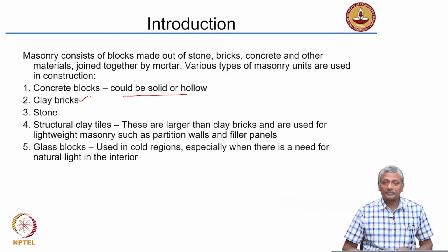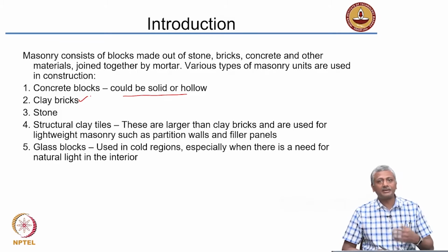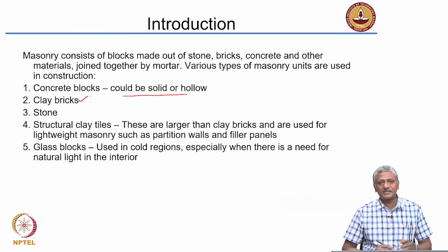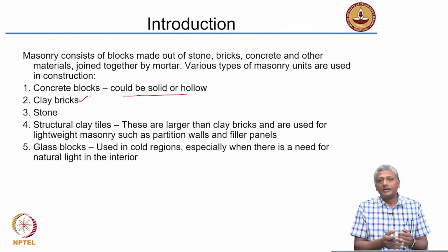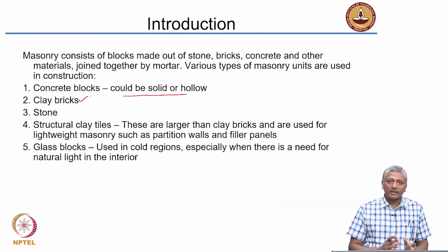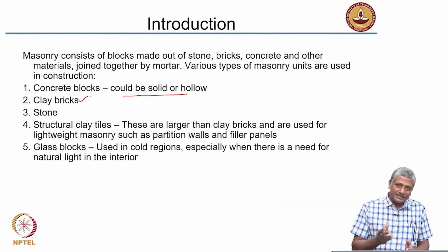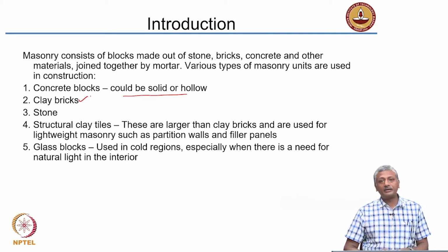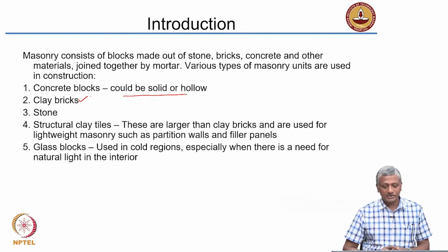Okay, so apart from these, there are also structural clay tiles. You can actually make structural clay tiles to bear load. So masonry, basically the components are bearing load. A typical tile which you put on the floor is not bearing so much load as a block that is supporting a wall. Okay, so structural clay tiles are designed to be larger than clay bricks and can be used for lightweight masonry such as partition walls or filler panels.